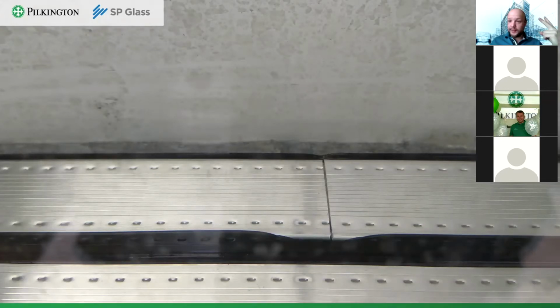The second factor in bent IG units is that butyl in bent IG units is always applied manually, because all of the bent IG units are made only manually, without any IG unit lines or something like that. And therefore, bent glass has a little bit of distortion which you want to compensate for, and you apply even more butyl. So there, butyl can expand even more than 2 millimeters. And that should be mentioned to the customer in the first place, even before the order is placed.